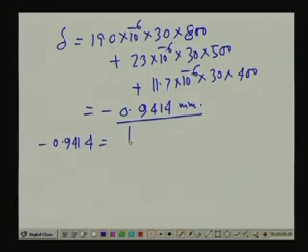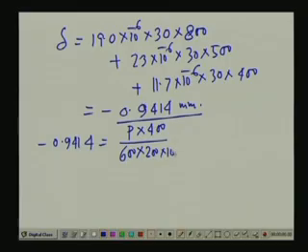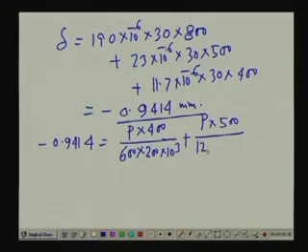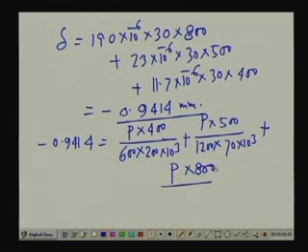And when we pull this by load P, then this elongation of minus 0.09414 is to be compensated by the force, which is P times L by A, which is 600 into 200 into 10 to the power 3, plus P times 500 by 1200 into 70 into 10 to the power 3, plus P into 800 divided by 2400 into 83 into 10 to the power 3.